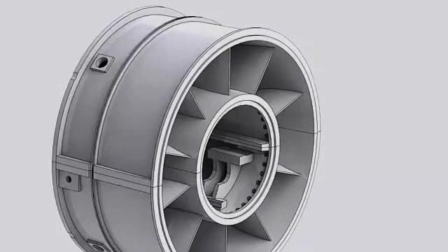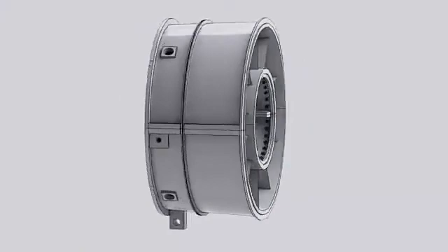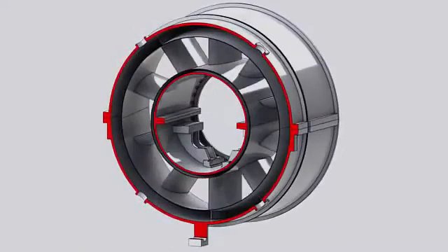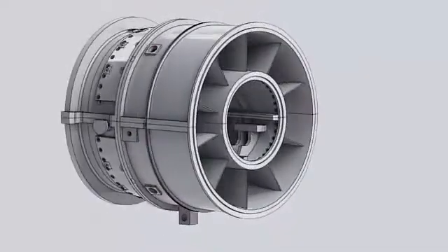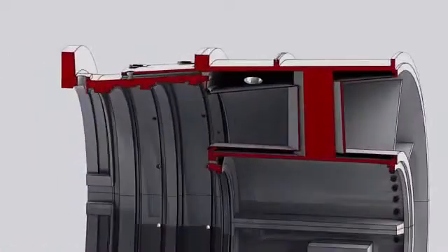This stability is required to keep the exhaust frame inner cylinder, which carries bearing number 3, in the accurate position, avoiding any misalignment. To ensure the temperature stability, air is forced by means of 2 off-base blowers between the exhaust frame outer cylinder and the exhaust frame diffuser surface through 4 ports. A portion of this air goes to the cooling holes around the turbine shell, and the remaining air flows between the struts and its outer airfoil-shaped fairing surface.